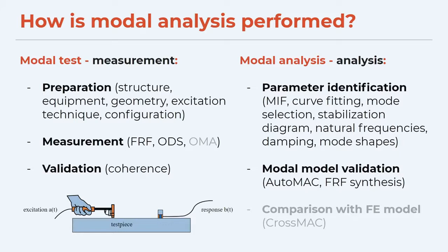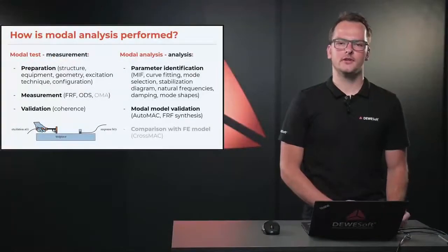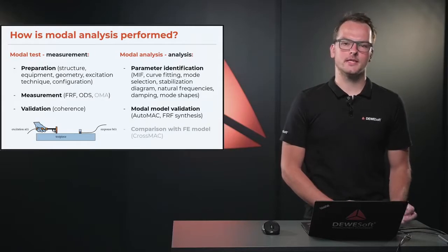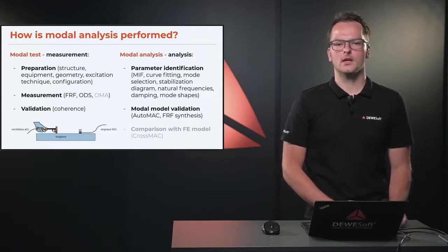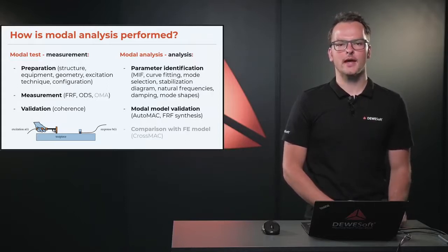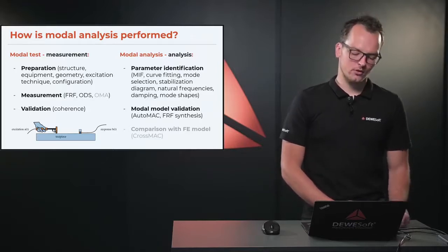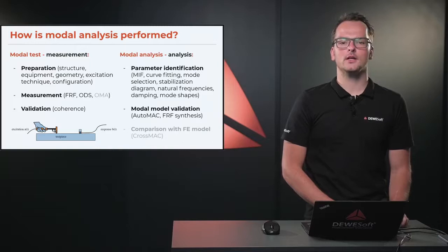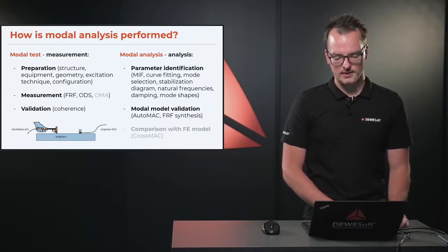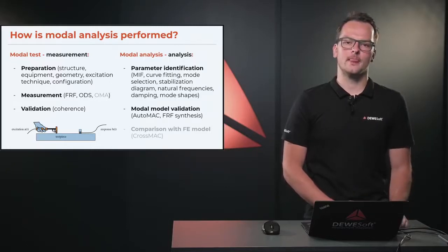And in this modal analysis module, we indicate modal parameters with the help of mode indicator function, curve fitting algorithms, stabilization diagram, and so on. And to validate the model, we use the AutoMAC and the FRF synthesis. So grayed out is also comparison with finite element model and also the cross-MAC matrix, which is currently not supported in Dewesoft, but we will add this also in the future.